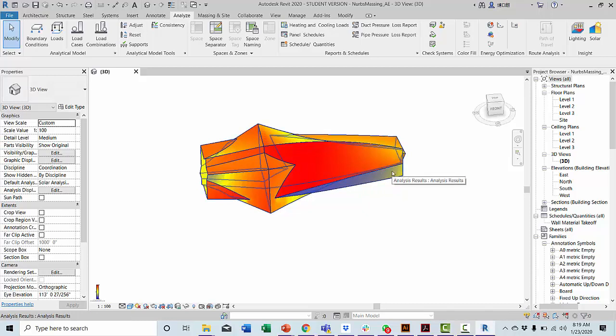So what are you going to do with that? You want to select those faces and think of them as the best ones for putting your windows, for instance. You don't want a lot of radiation coming to your windows, so you will look for the faces with less amount of energy coming through. These ones are going to be the blue in this case.